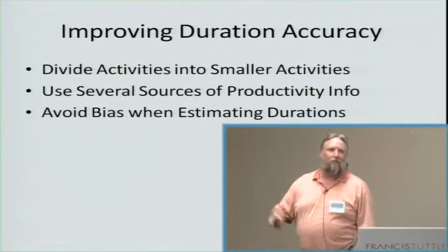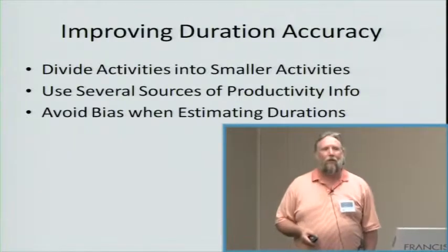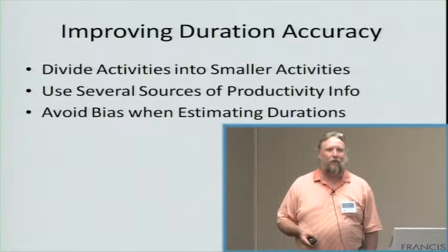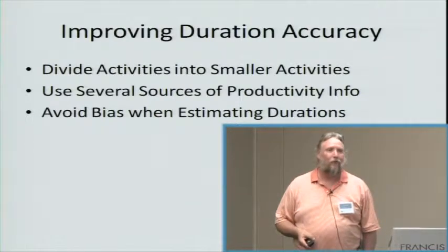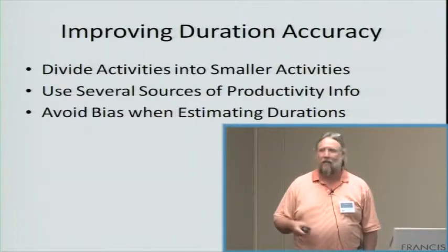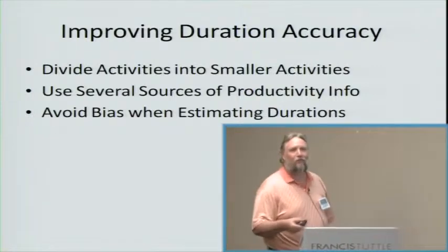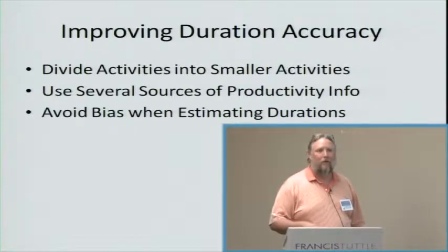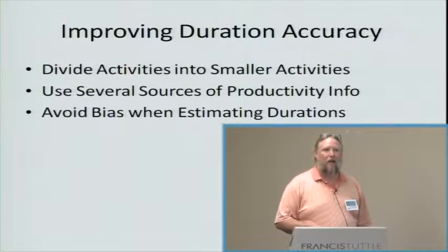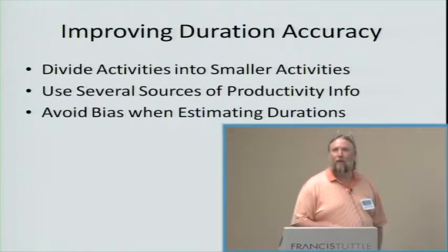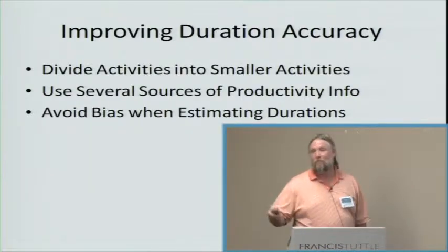So if I bias it by saying, you know what, I'm going to put this extra 50 yards an hour in there, that means I get an extra 3 or 4 days out of it, you're just going to eat those 3 or 4 days up because you know they're there. Okay? And that doesn't help you with your schedule because what you thought was free days, you knew were there, so it's like setting your clock 10 minutes ahead. You always know it's 10 minutes ahead. So you show up late anyway, because your clock said you were late.